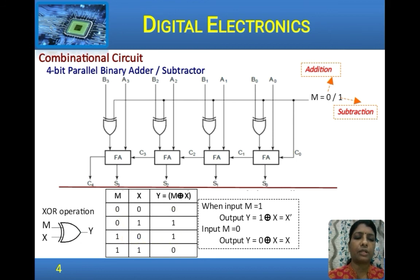If M and X are two inputs and Y is output, this is the output for an XOR gate. Here M is the input line that we give, either a 0 or 1. If M is 0, then the output is the value of X: 0, 0, 1, 1. Whereas when M is 1, the complement of the other input is obtained as the output. If X is 0, we get Y is 1, and if X is 1, Y is 0. That is, when M is 1, the output is X bar, and when M is 0, the output is X.